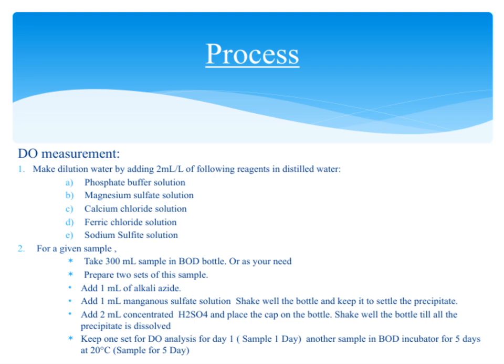Next, for each sample, we take 300 milliliters and place it into a BOD bottle. Of course, you can adjust the volume if your procedure requires. We then prepare 2 sets of this sample, one for immediate dissolved oxygen measurement and another to incubate for 5 days. To each set, we add 1 milliliter of alkali azide, followed by 1 milliliter of manganese sulfate solution.